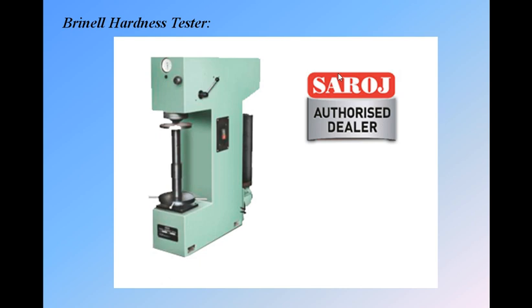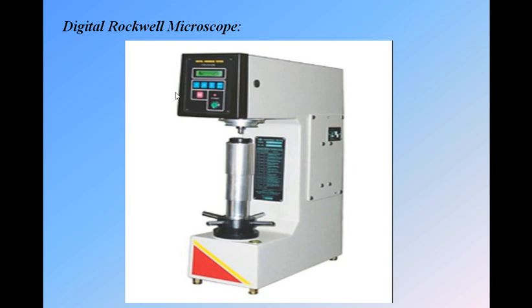Okay, next, this is the digital Rockwell hardness tester. This tester can be used to measure the hardness of those materials which have high hardness and low thickness, because here we have only loads of 50 kgf, 100 kgf and 150 kgf that can be adjusted from here. Here we have a knob, and on the basis of that knob we can adjust the load. If we want 50 kgf, 100 kgf or 150 kgf, we can adjust the load.